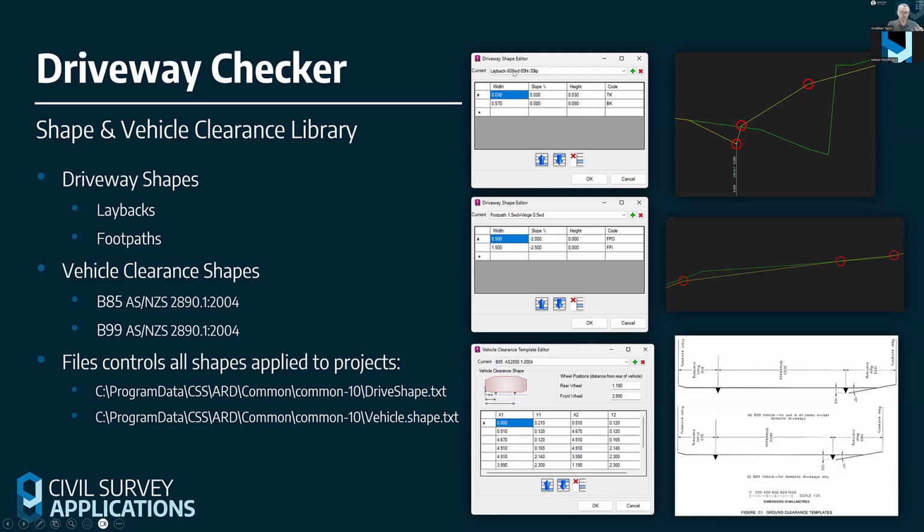And our standard library, this just happens to be picking one of the many listed in there, suggests a 30mm lip, which is what you can see here, 30mm high, 30mm wide, followed by 570 wide and 50 high. So 600 layback, making 80 high total. You can create these. You can also share them.